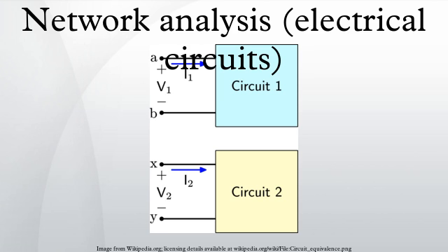Superposition. In this method, the effect of each generator in turn is calculated. All the generators other than the one being considered are removed and either short-circuited in the case of voltage generators or open-circuited in the case of current generators. The total current through or the total voltage across a particular branch is then calculated by summing all the individual currents or voltages. There is an underlying assumption to this method that the total current or voltage is a linear superposition of its parts. Therefore, the method cannot be used if nonlinear components are present.